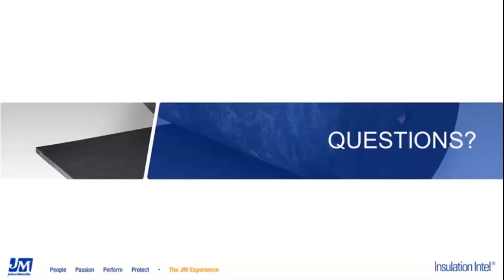But it's a tool where you can put in all kinds of different criteria, the material that you're putting the insulation on. You can adjust thicknesses, you can adjust the hot and cold surface temperatures, and so you can use that to calculate what different insulations may work within your system.